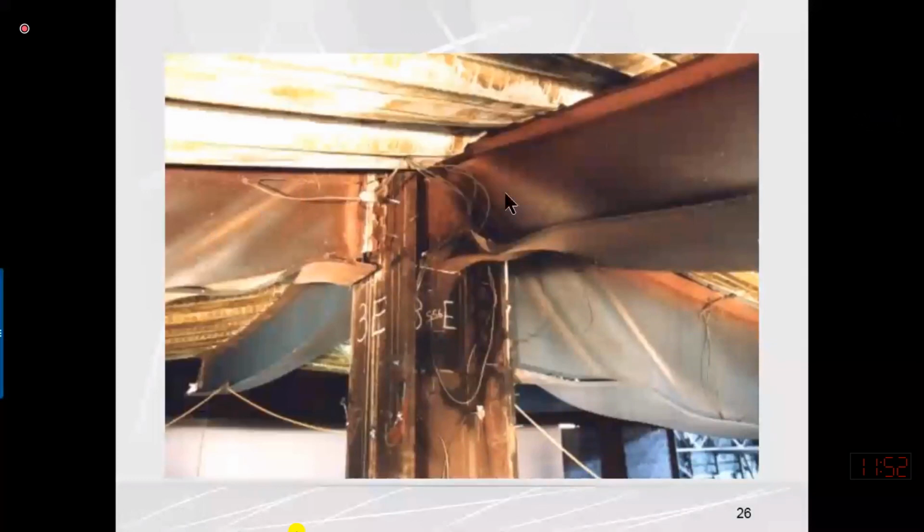If we cannot reduce the depth, we are supposed to use a thicker web, so that the height of the web over thickness of the web ratio should be lesser. So what are these governing limiting values? They are provided by AISC, so we may discuss them in our next lecture.